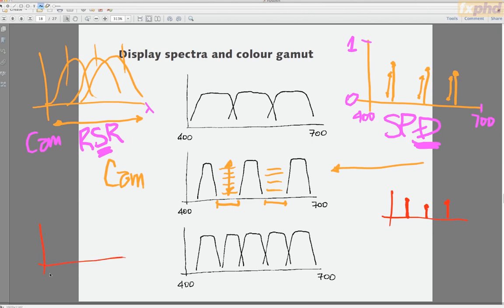If you've got a xenon or a UHP lamp that just has energy rather evenly distributed across the spectrum, one way to get wide gamut out of that is to have a whole bunch of primaries, like in this case, 5 of them. So this is called multi-primary, where multi just means more than 3.